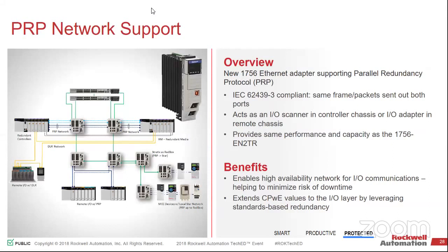A standard device level ring has a 3 millisecond uptime. So we call that a reconvergence rate. So if you pull the cable, within 3 milliseconds, the network heals itself. So all of the IO, in most cases, you have it running at about 12 milliseconds at normal. So the system doesn't see a blip. You'll get diagnostics on that. It'll tell you from what IP address to what IP address you broke the chain, but nothing happens to the overall network.